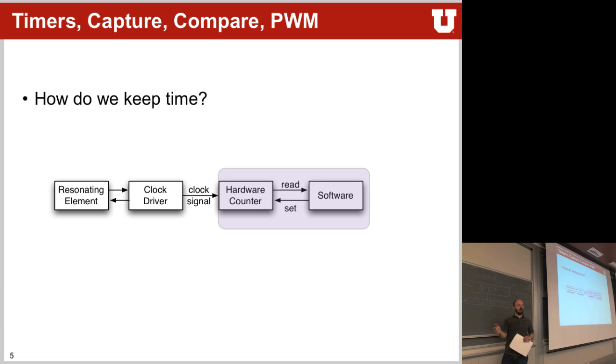But there's a problem with this logic. What can happen is that sometimes it can add a delay into your captures. So assume this happened at the time when this was metastable, but then your block delays it until you are in +1. Or sometimes they have to actually do it already a lot before this one here starts incrementing, just to make sure that you don't hit that particular time. So it can be that your capture is actually +1 or +2 later than the actual signal came in.